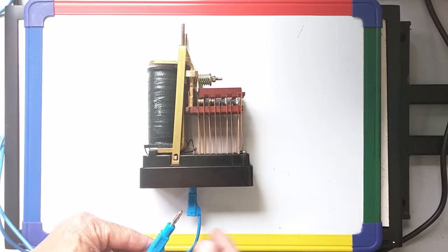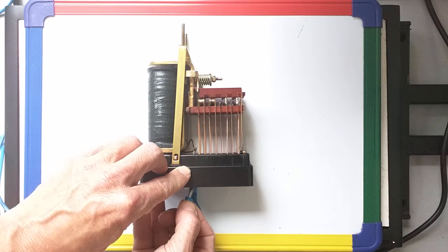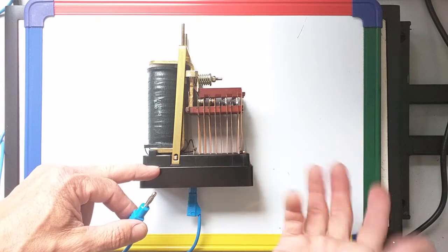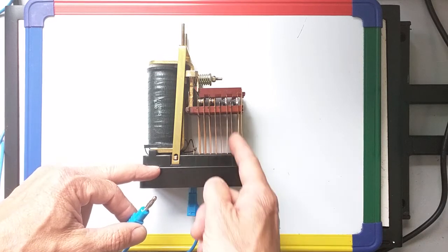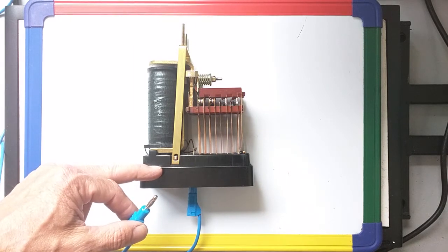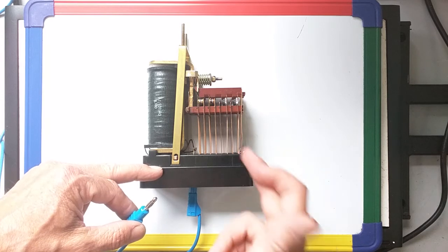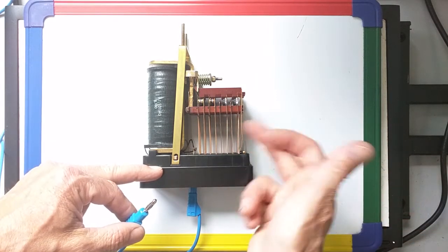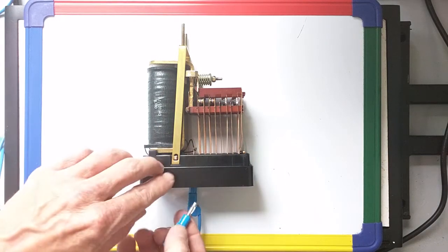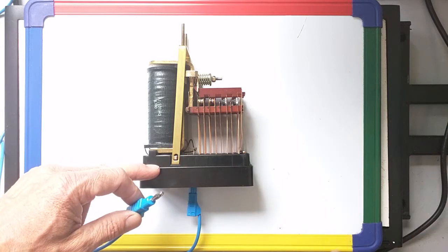An important thing to note is that although we put 24 volts on to energize the coil, these circuits can be any voltage. These are just like switch contacts, so they can be turning on any other electrical circuit at any voltage. That's another key point about a relay. Not only can you turn on and off several different things from one electrical supply, one signal, but these things can all be on different circuits at different voltages.